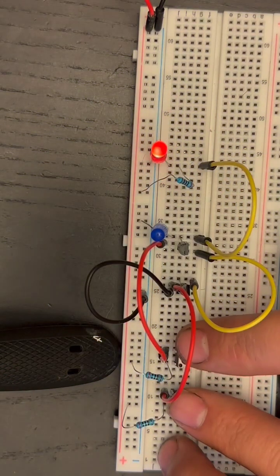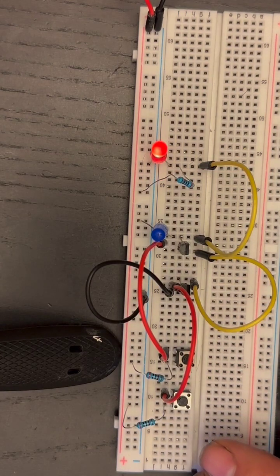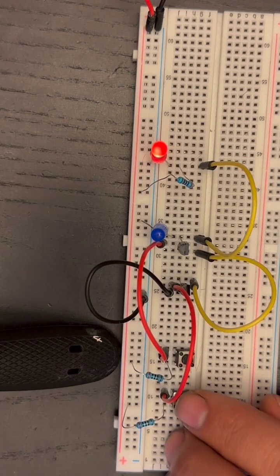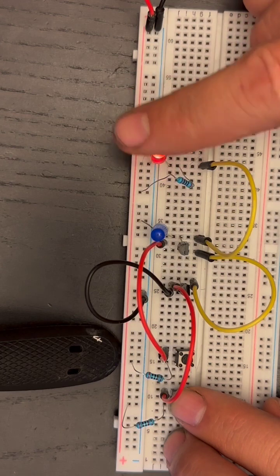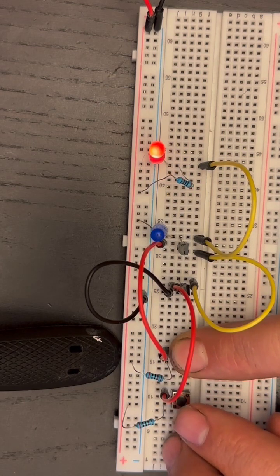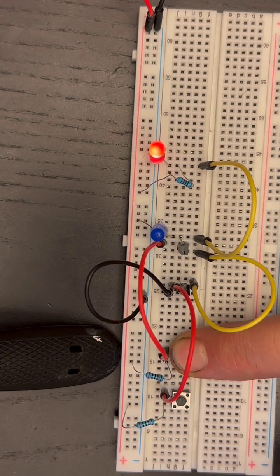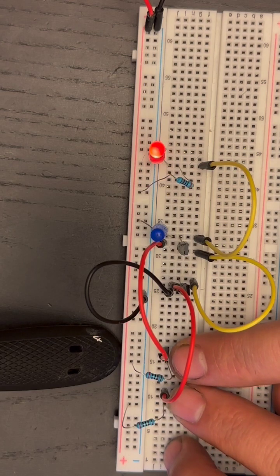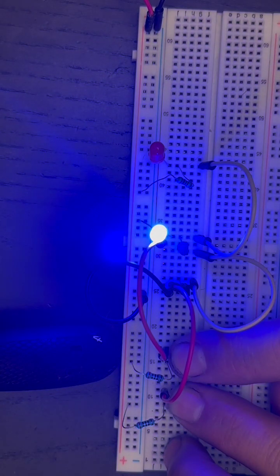For now, let's just keep that blue LED in there, even though right now it's an additional output that we wouldn't normally have on the gate. Here you can see if I push one of these, nothing happens. This stays on, just following our truth table, that when only one is on but not the other, this is on. And here you can see that the NAND gate is doing the opposite. It's still doing the opposite when just the other one is on. And if both of these go on, then our AND gate would go high, but our NAND gate goes low.